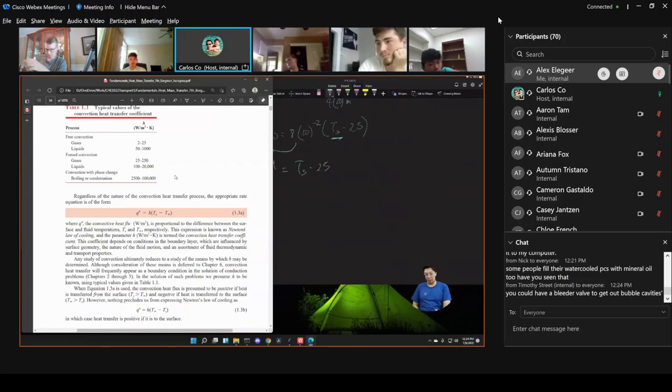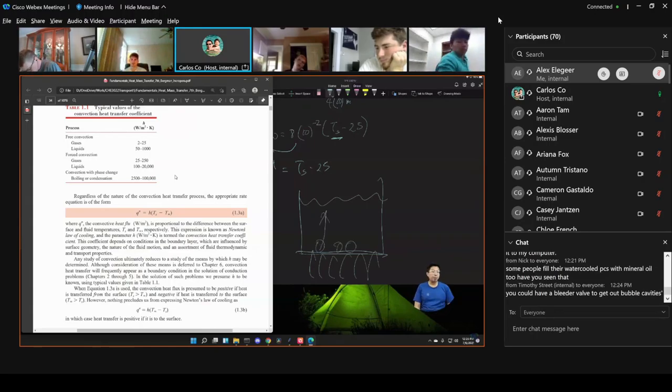Well, see, if you've got a pot here, so you've got your flames going in your water pot. What happens is the bottom surface gets hot, you start forming water vapor, and that water vapor goes up, so basically steam going up through the liquid. And that causes quite a lot of turbulence and motion, mixing effects right at the surface. That basically enhances the heat transfer at the surface there. You've got bubbles, water vapor that's forming and going up, and so that renews the surface there.